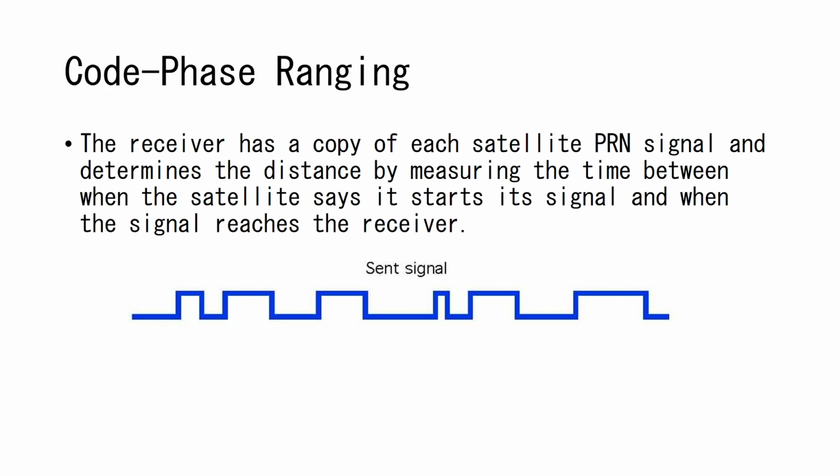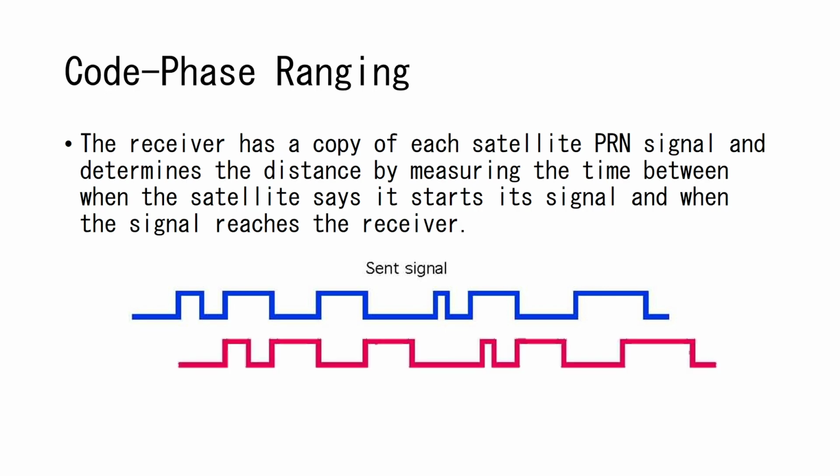It's going to then receive a signal from a particular satellite that it's locking onto, and it receives that signal. And based off of that signal, it knows that the pattern of that PRN is satellite number 3 in its database, but as it's replaying that signal in its database, it knows that signal is supposed to start, let's say, at 12 noon is when one of the signal cycles begins. Well, when it receives a signal, it's not at 12 noon, it's not matching up correctly. It lays them over top of each other with when it's received, what it should be reading at that particular point in time. And so it knows there's going to be an offset here.